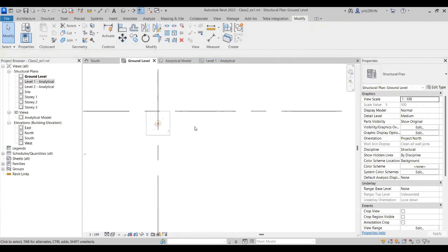That's why when the engineer does the modeling, you have to be a bit cautious. What tool are you using, and how is it going to affect your analytical model? Otherwise, this is always happening in our office. After people do the model, when you open it, it cannot be exported because the wireframes are not connected.